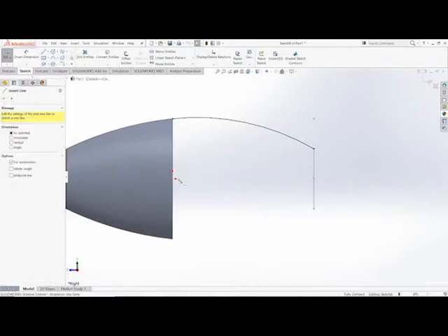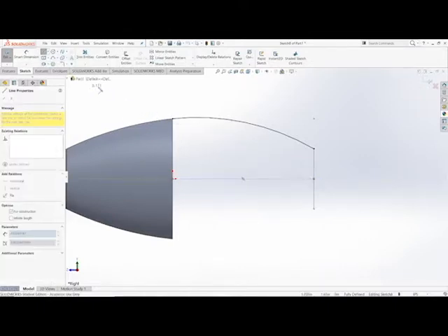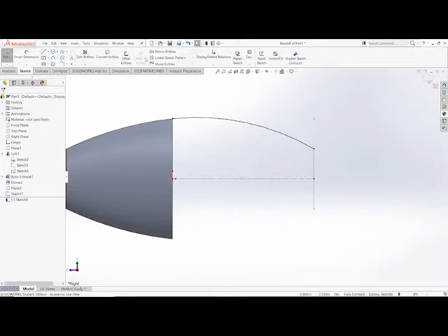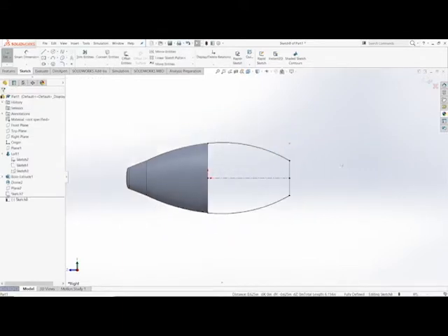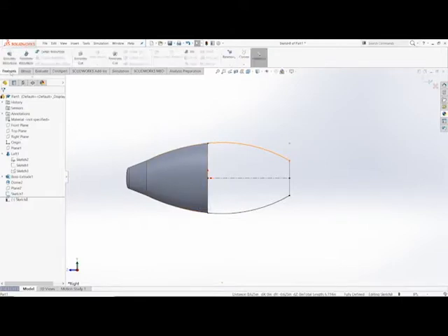So, make another center line. You cannot use a point. You cannot do it with just a point. I actually learned that the hard way when I thought maybe I could just select a couple points so I don't have to draw a line. No, it doesn't work that way. You have to use a line. I used a point and it crashed and I lost my progress. It was really annoying.